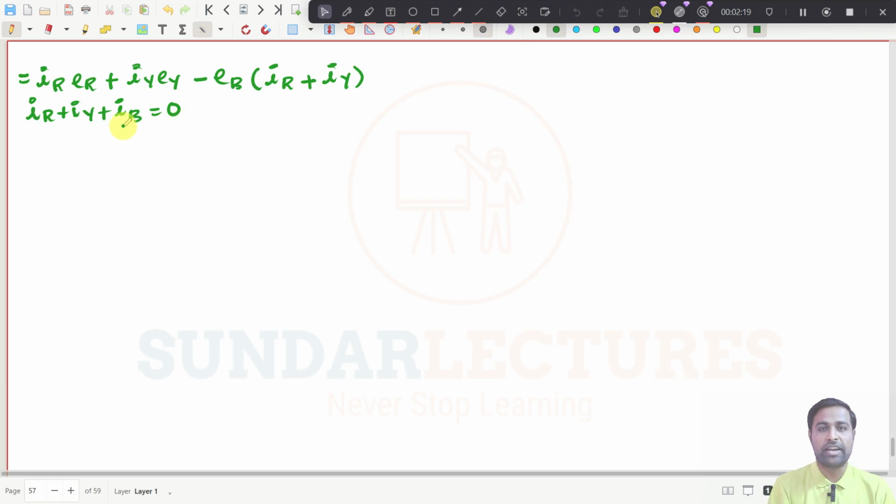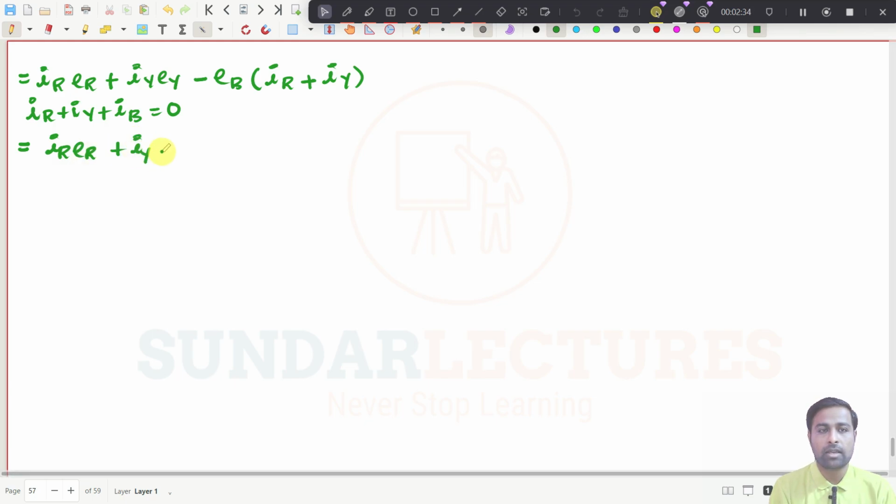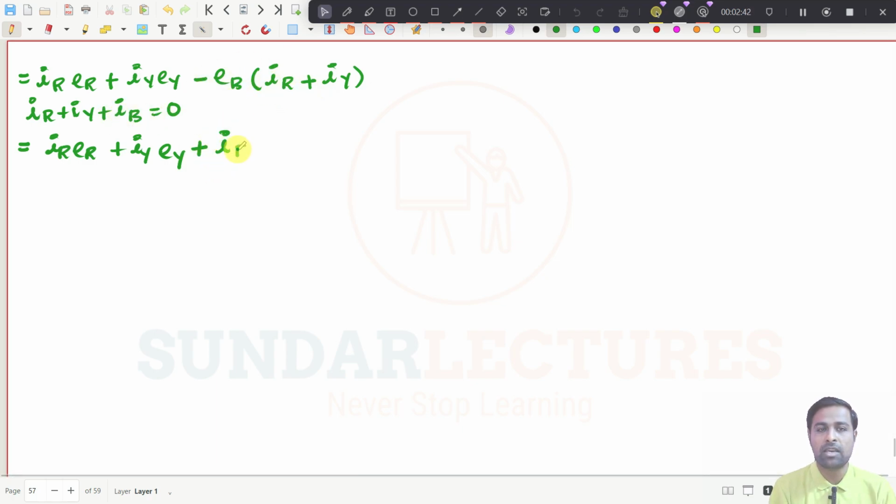So you see here. Now what I can write here, instead of IR plus IB, IR plus IY, I can write minus IB. I can write minus IB, right? So if I write that one, it is IR ER plus IY EY. See here, if I put minus IB, then it will be plus, right? So it will be plus IB into EB. This is the total power.